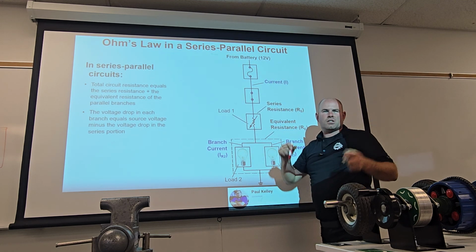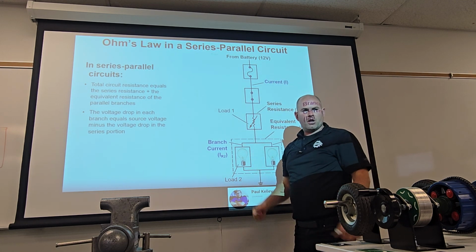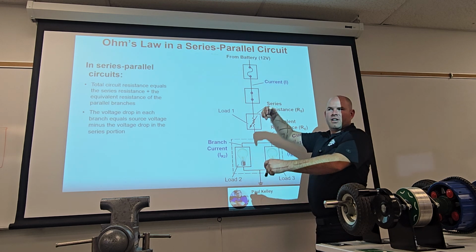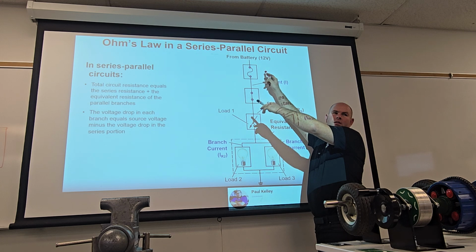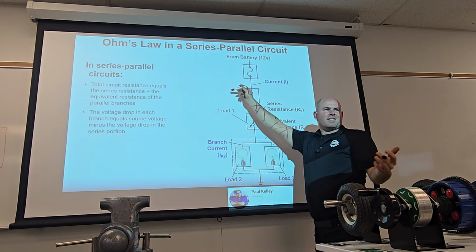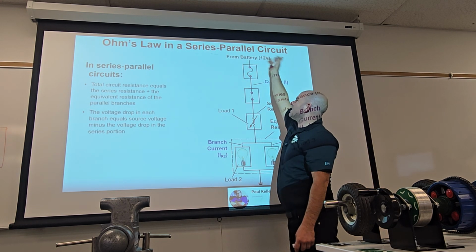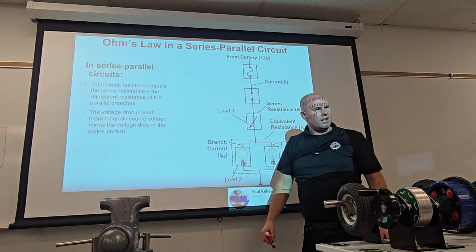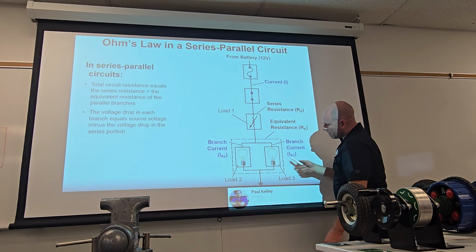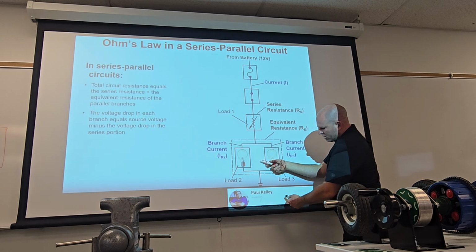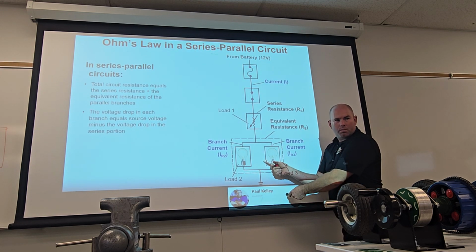Make sense? OL just is open. If I disconnected it, shouldn't it be open? If I disconnected it and I measure it and it shows 0.2 ohms, what's that tell me? It's still connected. Why is it connected if I disconnected it? It's because it's shorted, right? Same with the ground. I would disconnect the ground. I'd put my meter here. I put my meter on the ground. And if it's disconnected, it should be open, right?